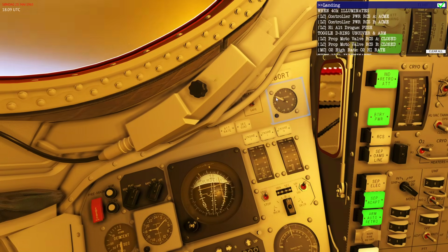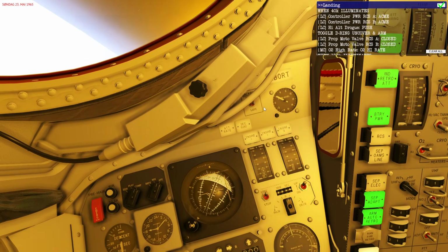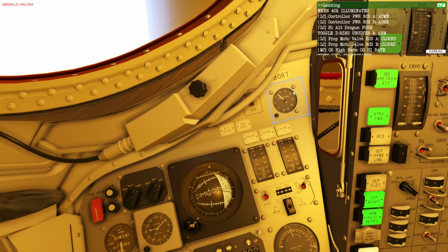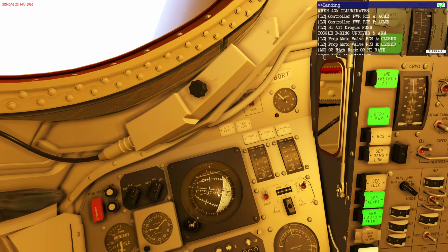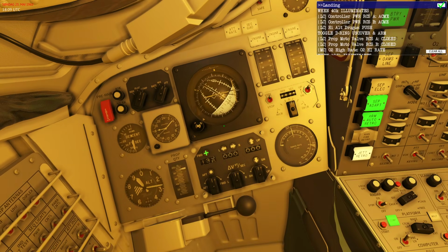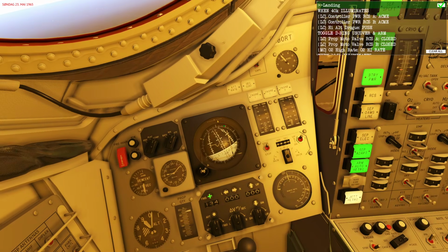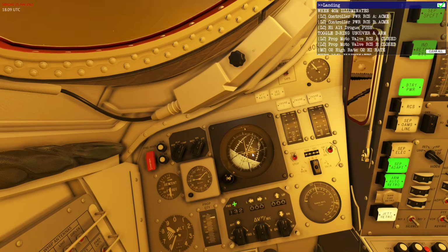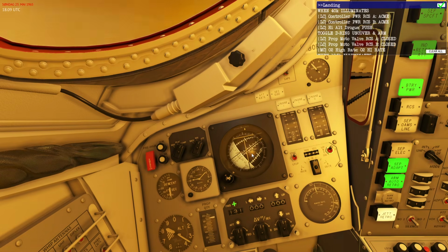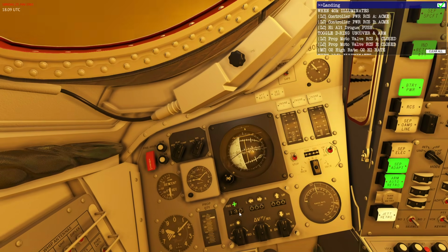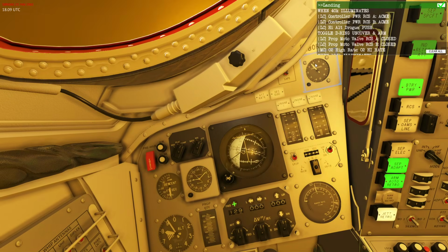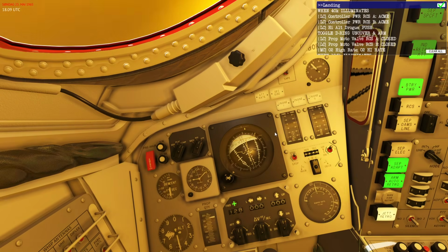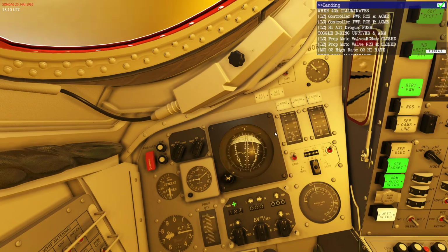Now it's going to start to continue to build up, but it won't exceed the 12G limit, because I'm now having a constant roll. And if I would like to be longer in the air, that's traveling longer on Earth, to reach that, I should have now pointed my lift vector upwards to extend the length that I'm going to be flying through the atmosphere.